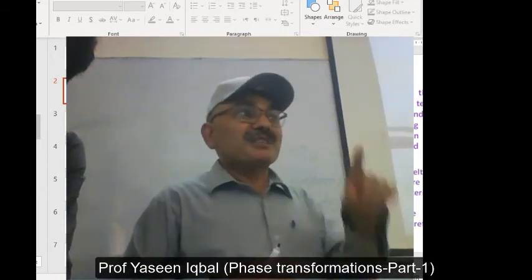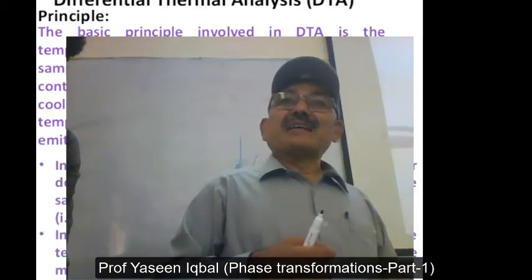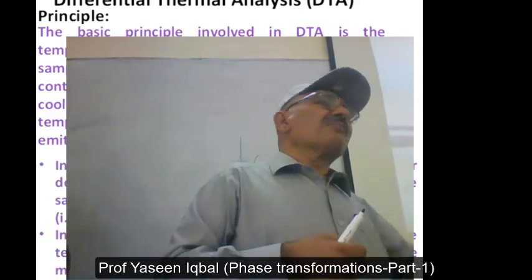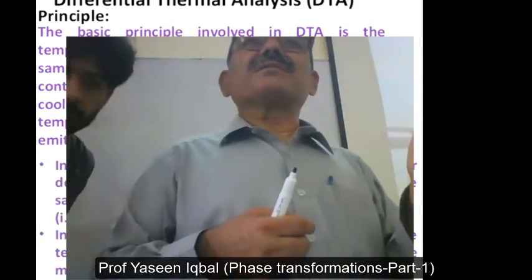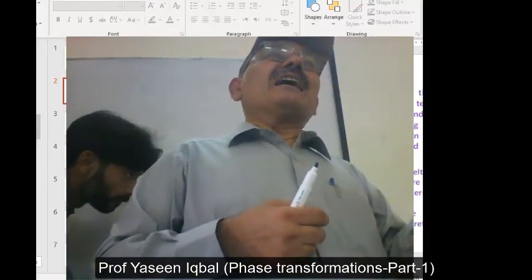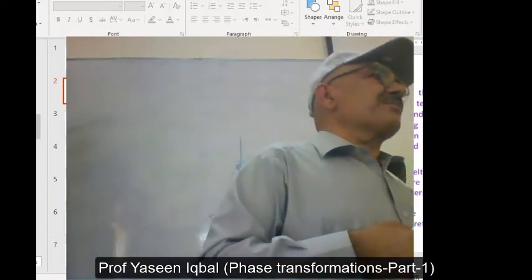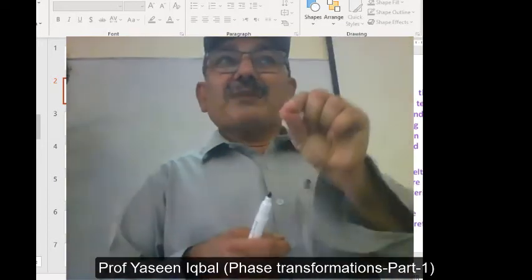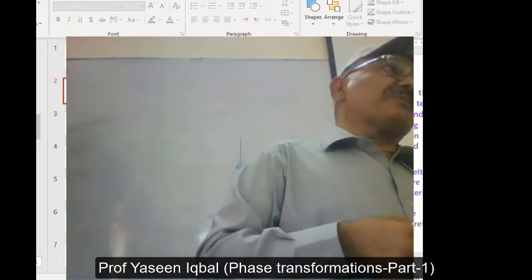But are you interested in big crystals? If you are interested in electrical properties, then you need minimum grain boundaries, because the grain boundaries enhance the power loss. Grain boundary, technically, scientifically, is a different phase, because the behavior of the material in the middle of the grain is different than the periphery or border of the grain.